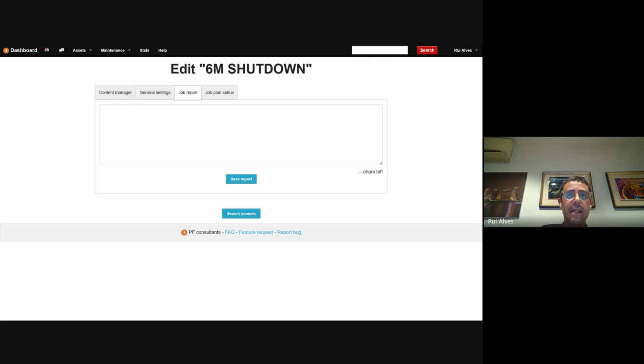So this is 3 days after you finish the shutdown, and you've got some time to reassess and ask people what they think about the sequence of works. And perhaps you realized, as I said in the beginning, that you planned something that would last for 2 hours, but in fact, it only lasted for an hour. Also, maybe you made use of outside contractors. You called 4 guys in, and most of the time they were doing nothing. Now you can leave a note to say that you actually needed only 2 for jobs of this type.